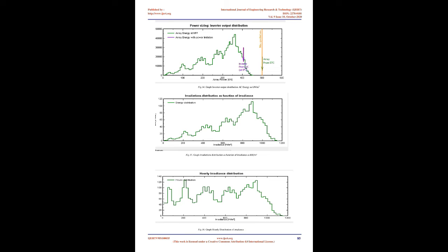Loss evaluation. In this mode the only energy loss is the difference between the PMPP potential power and the PNOM DC limit effectively drawn. We can see on the power distribution diagrams that even when the inverter's power is a little bit under the maximum powers attained by the array in real operation, this results in very little power losses, violet steps with respect to the green ones, quasi-invisible. The simulation and the analysis of the overload loss is therefore a very good means for assessing the size of an inverter.